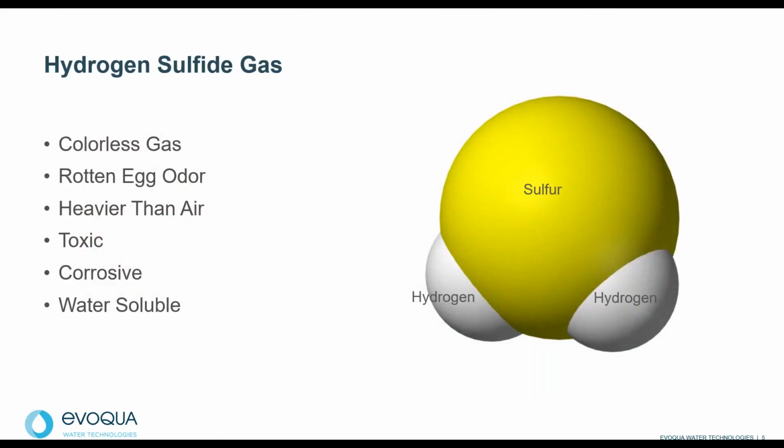So hydrogen sulfide gas is an inorganic odor. It's a colorless gas characterized by a pungent rotten egg odor. It is much heavier than air, forming in wastewater and capable of escaping from wastewater into air and enclosed air spaces. It is corrosive and must be eliminated from wastewater using chemical dosing equipment, for instance, liquid phase chemical technologies,